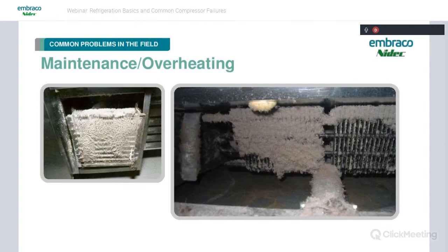And then, of course, there's maintenance. We see a lot of just plain lack of maintenance, either by not knowing or people don't want to call for service. They don't want to pay the service technician to come out and maintain the system. Obviously, especially in a commercial environment, you're going to see this type of buildup on the condenser coil, and then your system can't reject the heat anymore. So it's just going to sit there and heat soak. It's going to heat up the oil.